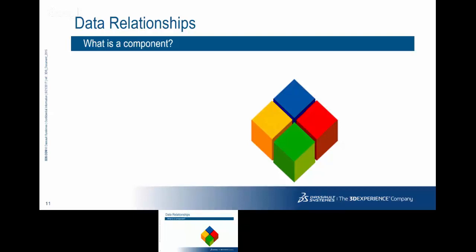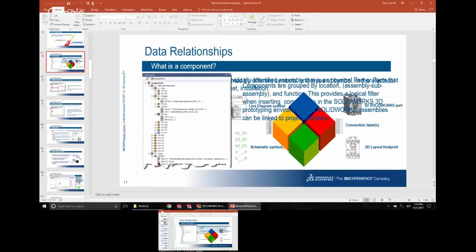When I actually go in and show you what I'm going to do to the drawing, we'll see that we can insert a symbol and not have manufacturer part data associated with it at all, and vice versa. You can have a component with manufacturing part data but no symbols. Think of those as splices, butt splices, or screws, or anything like that, because that component list is going to be your bill of materials. Okay, you guys with me so far? Cool. I see nodding. That's good. And hopefully if anyone's online, you are nodding as well.